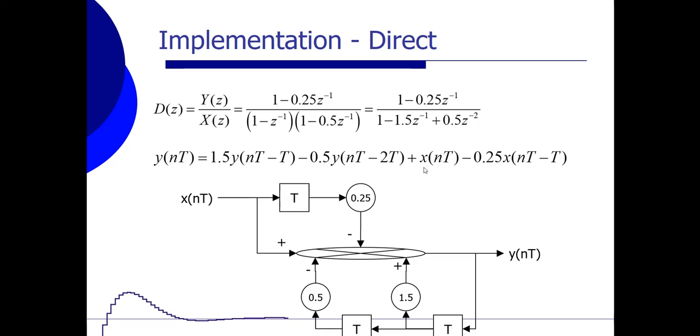And then we start off with the input and with the delayed inputs. Then we draw the output, and we add to these inputs the delayed output and the delayed output, which is delayed 2 samples. So that is that expression. And then we add everything up with the correct signs, minus over here, plus over here, minus over there, plus over there, and then we get the output.